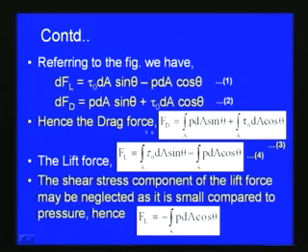In a similar way, as far as the lift force is concerned, we have seen the lift force on the elemental area in equation number 1. We can integrate this expression, equation number 1, so that we get the lift force FL equal to integral over the area A of tau 0 dA sin theta minus integral of P dA cos theta over the area A, as in equation number 4. This equation gives the lift force for the body which we consider. So equation number 3 and 4 give the equations for the drag force and the lift force for the case which we consider.